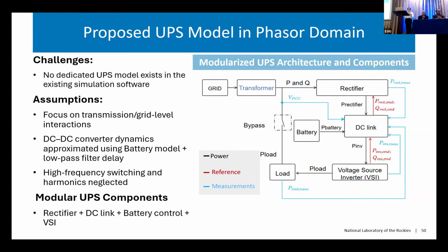So we could simulate the whole control logics here and make sure how those batteries can be tested when you have different control designs for your rectifier, batteries control, that DC-DC boost, and also this VSI. So you could have very different performance for your UPS and try to understand it when it's operating at different operation modes, what services or what dynamics it can actually provide to your grid.